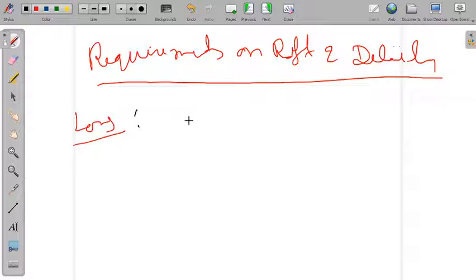The code book says that the minimum longitudinal bars should have a cross sectional area not less than 0.8% of the gross area of the column section.